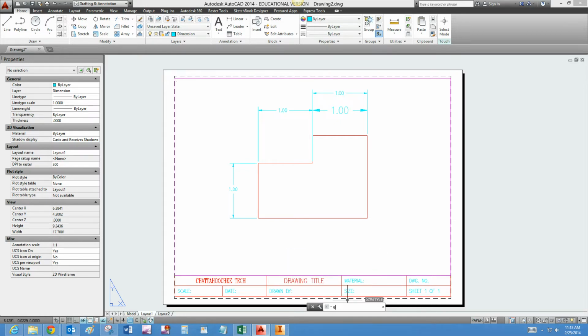Okay, so again, when the decimal inch dimension is used on drawings, a 0 is not used before the decimal point of values less than 1 inch. However, when the metric dimension is less than 1 millimeter, a 0 precedes the decimal point. Okay, so just to let you know, I wanted to share these dimensioning rules with you.